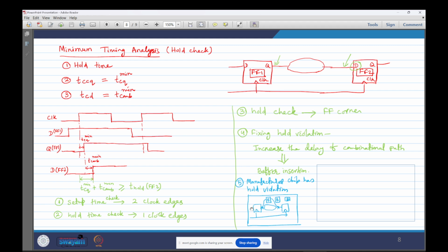Let's say I have two flip-flops and I have a hold violation in this path. Since the FEOL and everything up to metal 1 or below is manufactured, which is the expensive part of the chip, what people can do is only change the metal 1 mask and reroute this small portion to avoid this hold violation in this path.